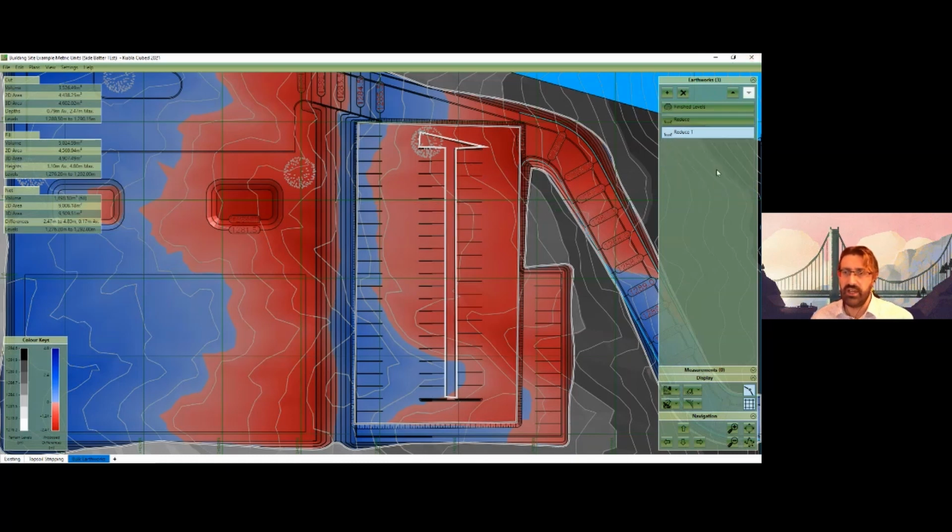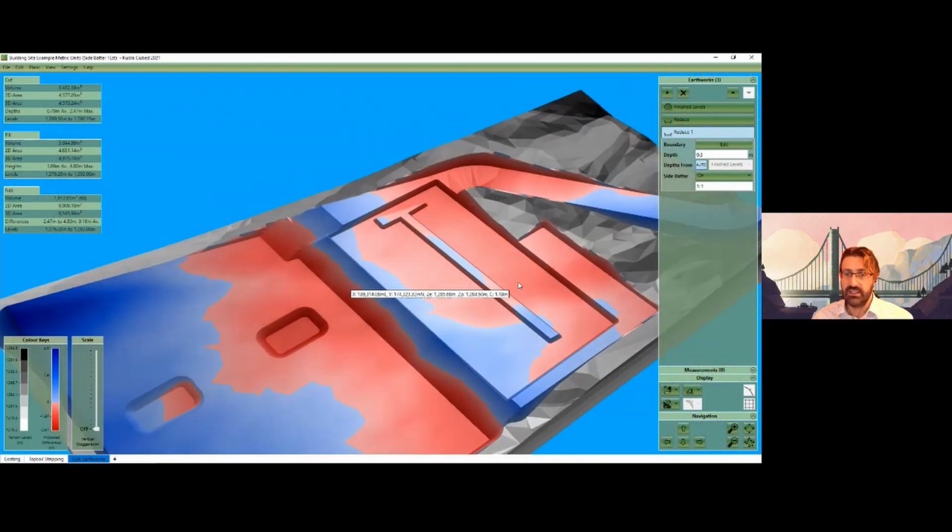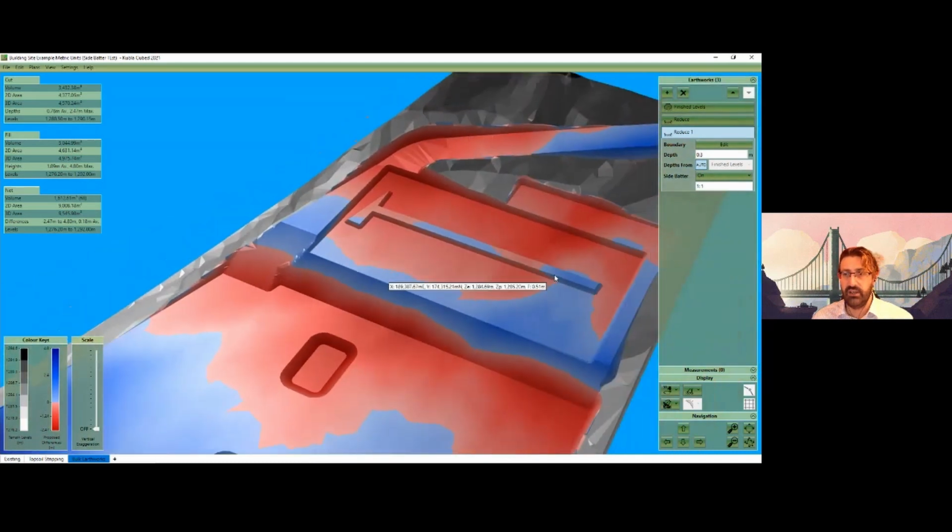So instead what I know now is that this one, if it's also set to auto and from finish levels, actually overwrites this one, so I can set this one to 0.3 and that section will be 0.3. This area here will be 1. So it's a really powerful system and really upgrades the capability of the subgrade adjustment functionality.